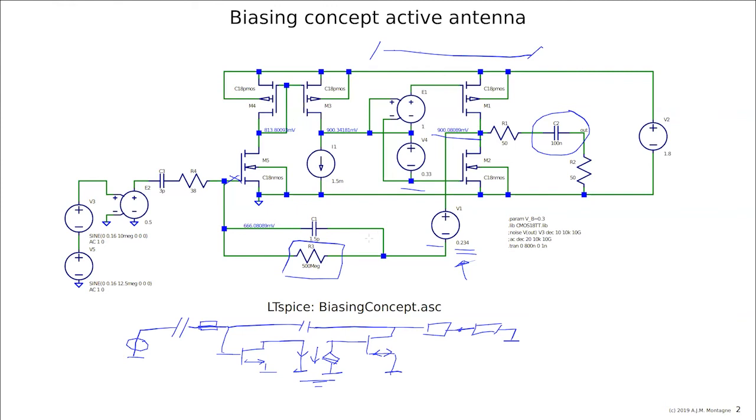But this is a solution, and we have designed the noise behavior, we have designed the bandwidth and the stability. We could not check the linearity. The only thing we have done was we have designed the output stage so that the drive capability of the stage is large enough so that we know we can handle the signal that we need to handle. That is what we have done.